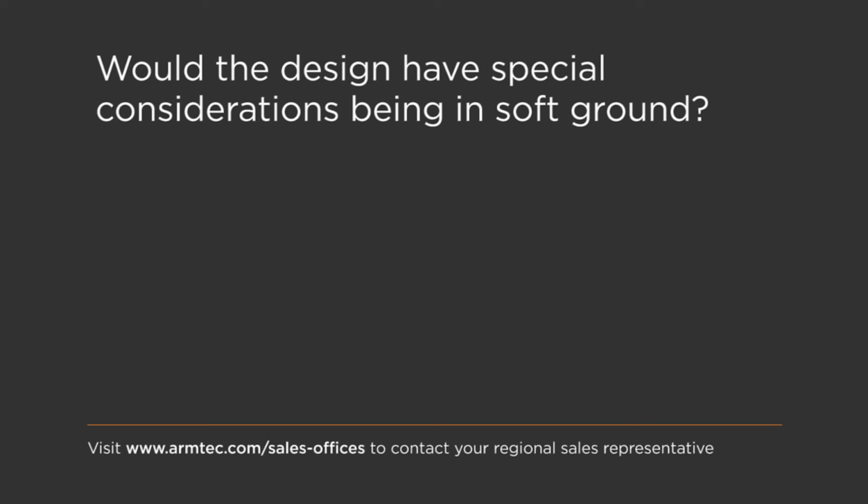Yeah, so if I understand the question correctly, that person is asking whether the design would have special considerations with being on soft ground. Generally speaking, full periphery structures are better suited for applications with lower than normal foundation bearing capacities. But to a point, at the end of the day, these structures are going to be buried, and the foundations will have to support the weight of the structure as well as the soil column above it. So the foundation capacities will have to have sufficient strength to support that. That is usually best designed by a geotechnical or foundation engineer that will be able to address that.